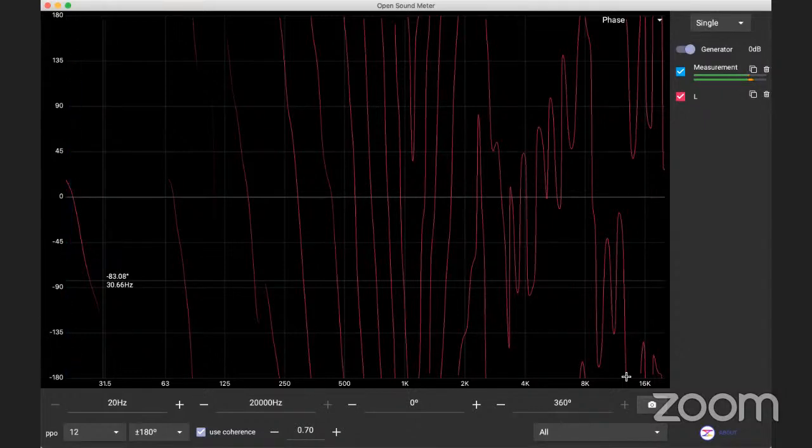Say for example, if I'm standing here, I have a particular relationship with the left and right speaker and the center speaker. But the moment Atharva comes and stands there, his relationship with the speakers is completely different. So his ears and the speakers have a different phase relationship. Phase is always relative. You cannot have phase of one speaker. You can have phase of two speakers, because you're considering one speaker and then the second speaker, comparing the two and seeing at which point you are standing, whether they're coming together in phase or not. So it's a very complicated thing. But if you understand the basics of it, you'll know exactly what you can compromise and what you cannot compromise.